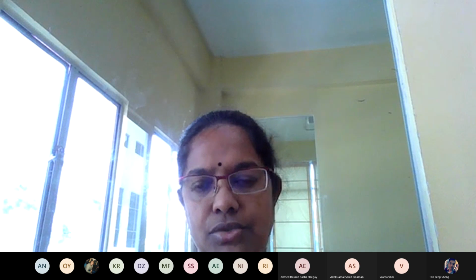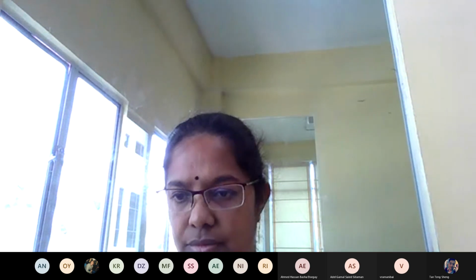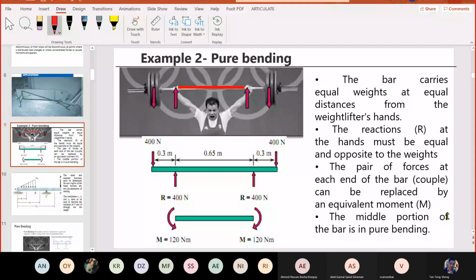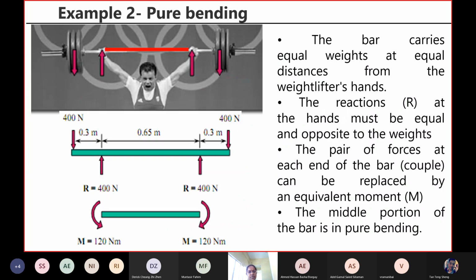Come on, let's continue with this. I will provide the table like this. Okay, coming here. See, this is changed to moment. 400, when you calculate the moment at this point, start from this end. Either you can resolve from left to right or right to left. At this point means you can come from this to this or this to this. But the simple one is to go from left to the point where it is necessary to calculate. 400 times 0.3, right?